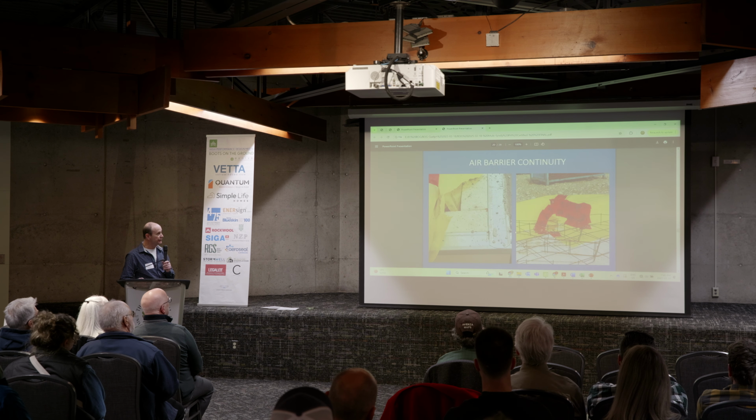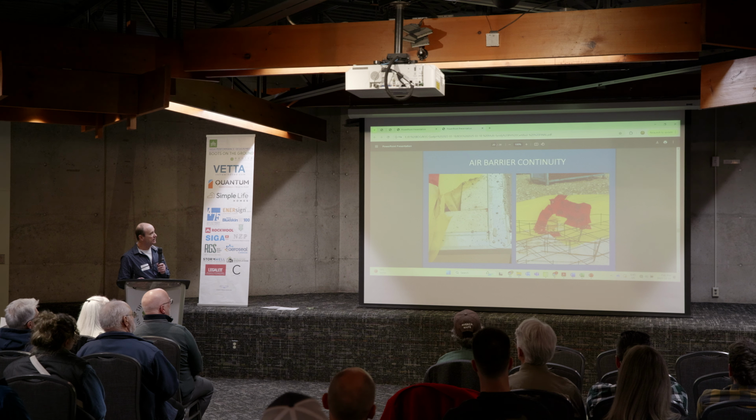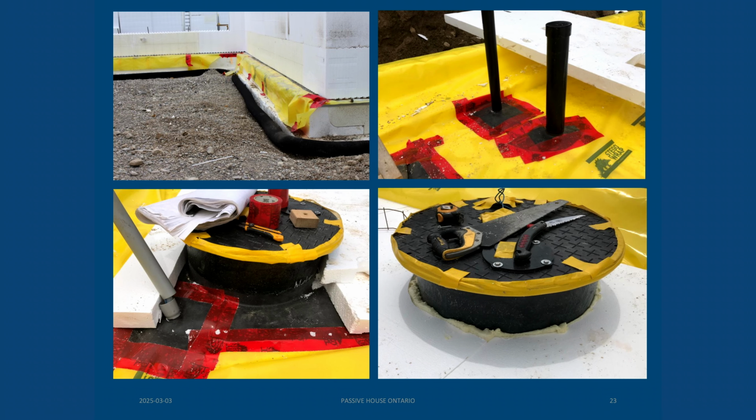The devil's in the details for air barrier continuity. I'm just showing this not because they didn't do a good job, they actually did a great job, but this is a typical detail where in the corners, where you have different sheets of membrane coming together and you're trying to maintain continuity, it can be problematic to get it to go together properly. So this is the right thing to do, and not leave it like what you see on the left here. A lot of careful detail through all the penetrations, mostly for maintaining air barrier continuity.